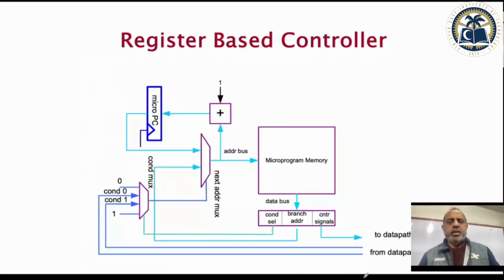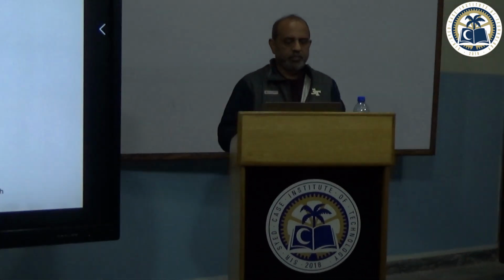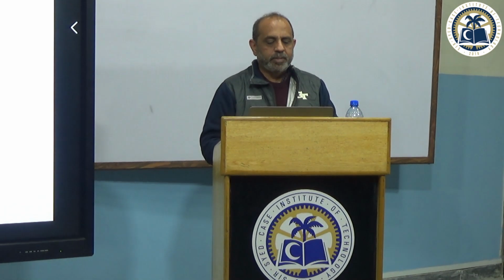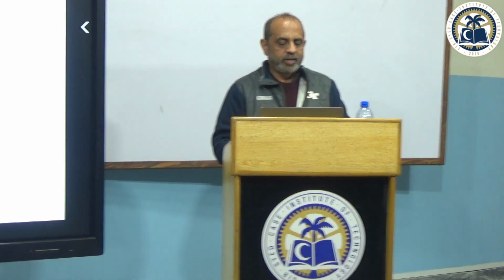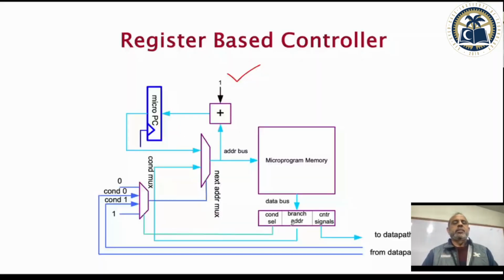And now it is getting in shape. Why put a counter? Why not put a program counter register which always adds 1? A program counter register always adds plus plus plus plus plus. It keeps on adding 1, except once you have a condition, and that condition would have not the address coming from the program counter register, rather the branch address which you have given here.